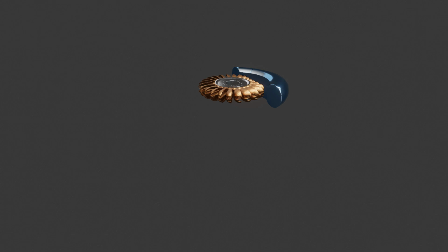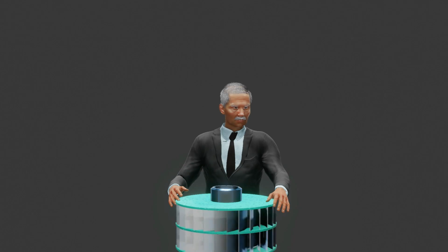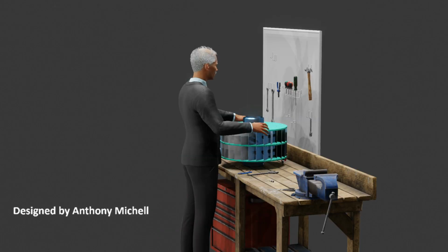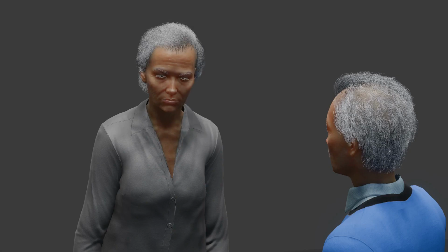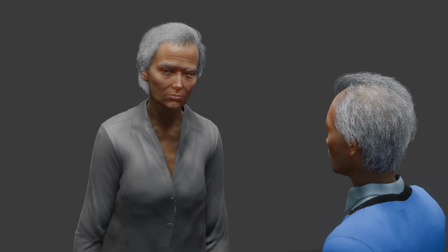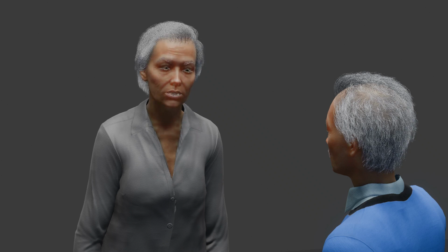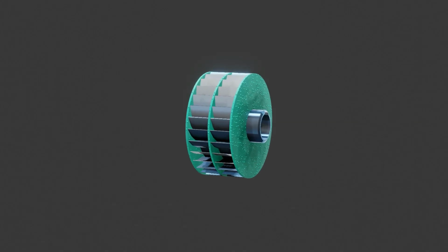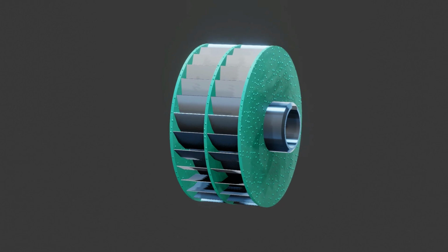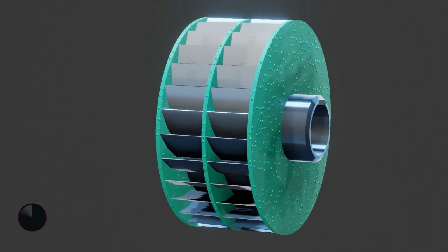On the other hand, a cross-flow turbine was designed by Anthony Michel, an Austrian engineer, in the early 1900s. Later, Donát Bánki, a Hungarian engineer, improved upon it, and it was improved even further by German engineer Fritz Ossberger. A cross-flow turbine is drum-shaped and uses an elongated, rectangular section nozzle directed against curved vanes on a cylindrically shaped runner. It resembles a squirrel cage blower.